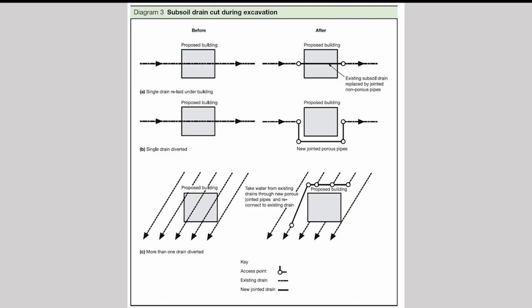The next part of it is also to take a look at groundwater. Now, building regulations don't per se deal with flood risk assessment. But ideally you want to have done some flood risk research anyhow. But one of the things to look out for is, are you likely to be cutting across a site where there's groundwater movement within it? Because you'll then need to create subsoil drainage. Otherwise, you'll end up with increased amounts of moisture or groundwater potentially driving into your site itself. And that's something that's quite often forgotten about.